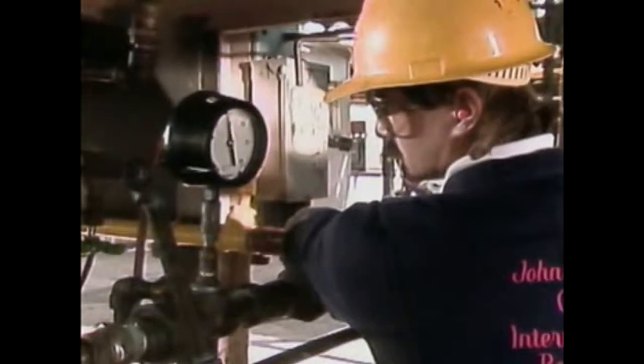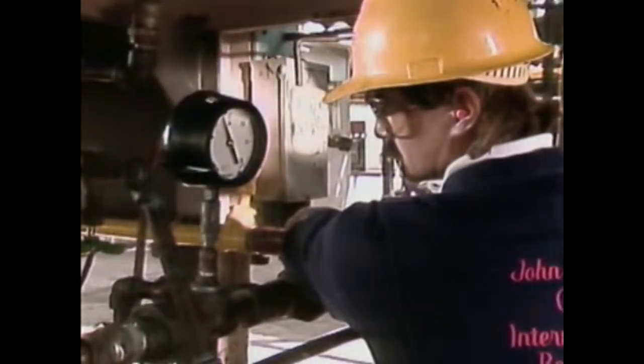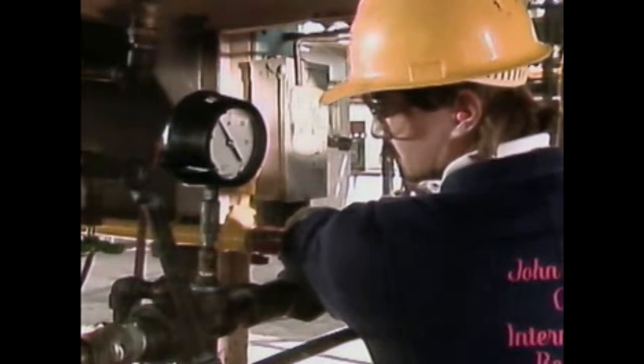An abnormally high fuel pressure could lift the flame off the burner. Therefore, decreasing the fuel pressure corrects the problem and brings the flame back toward the burner. If the fuel pressure is too low, the flame could burn inside the burner tips, producing a whistling sound. Most of the flame patterns and burner adjustments we've seen are for gas burners. Oil burners are operated a little differently.